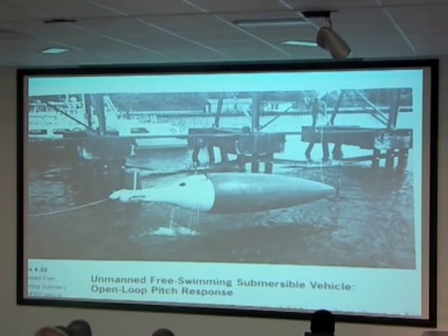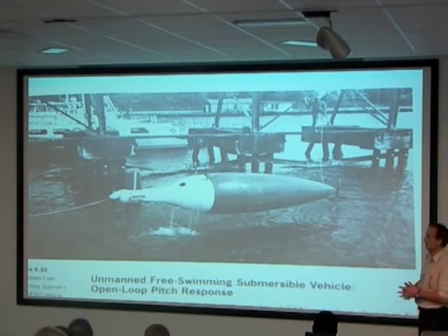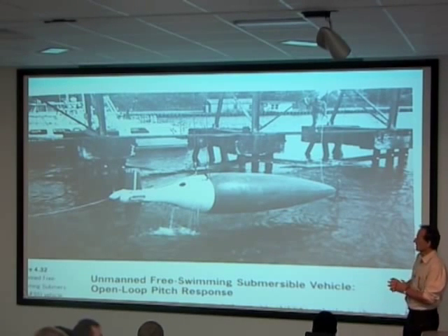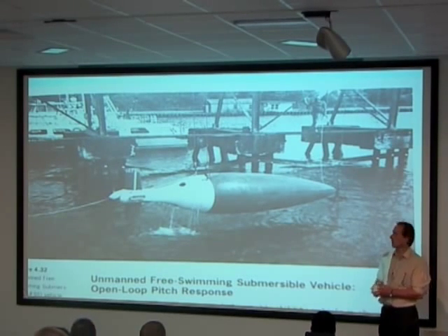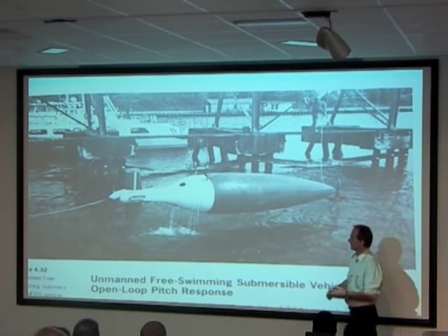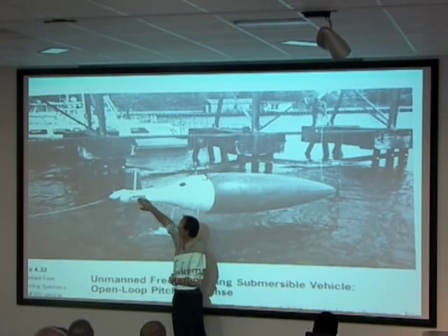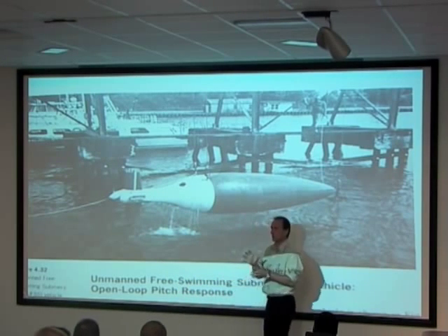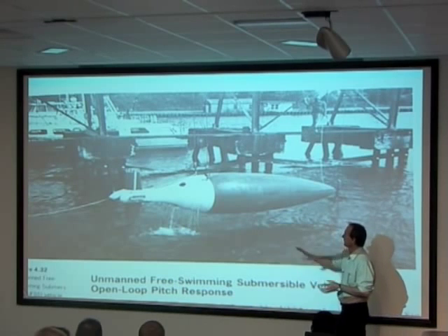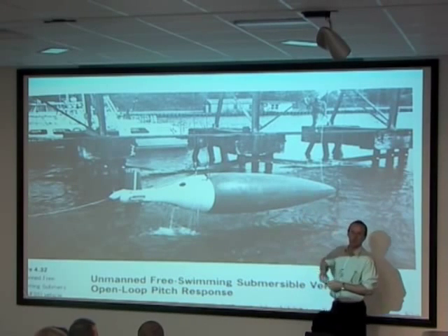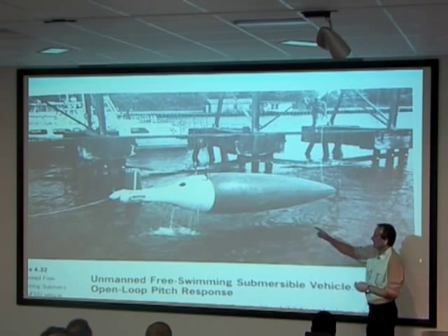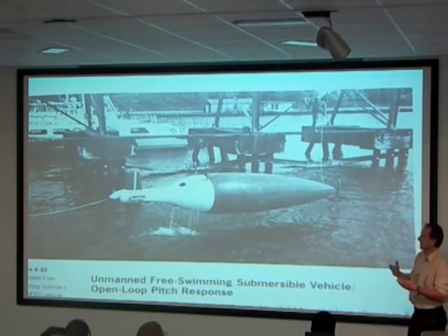And what I'm going to be looking at, just to talk through the use of compensators, is the response to changes in pitch angle. So we've got these elevators, if that's the right word for them, I'm not sure, on the back of the tail there, and we're going to look at the relationship between the pitch angle of the vehicle and our input into those actuators.